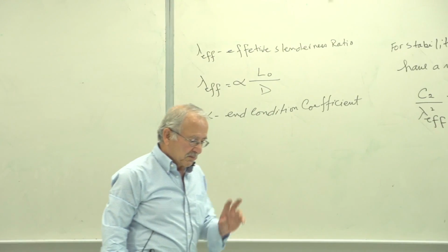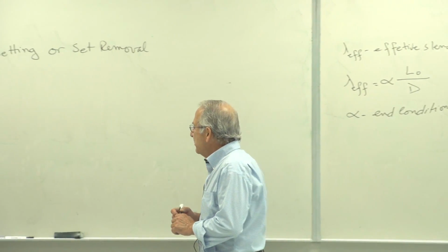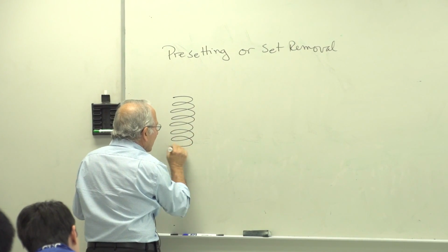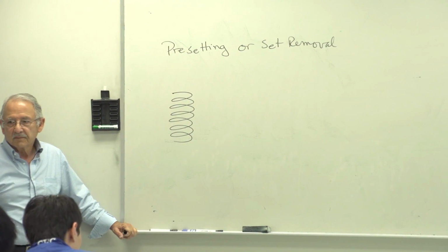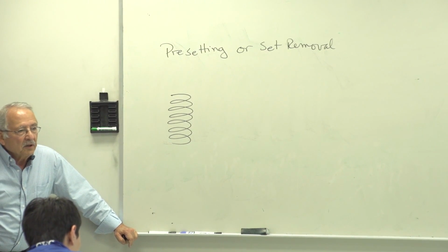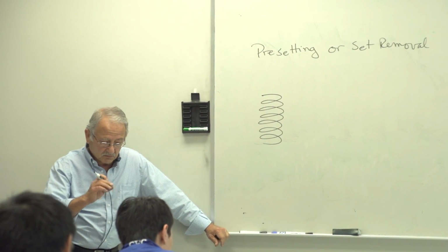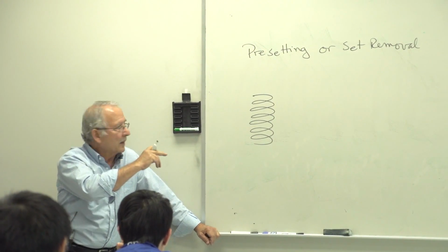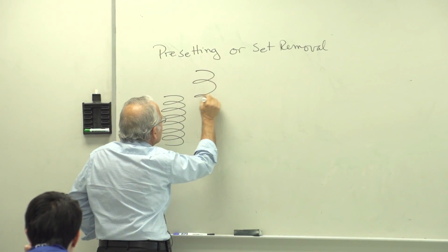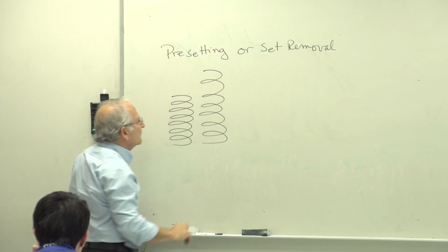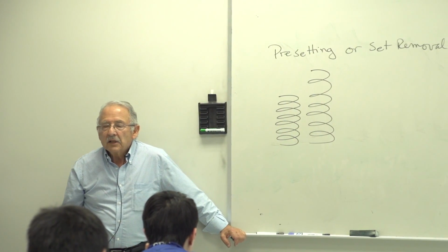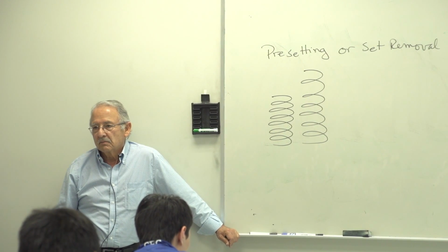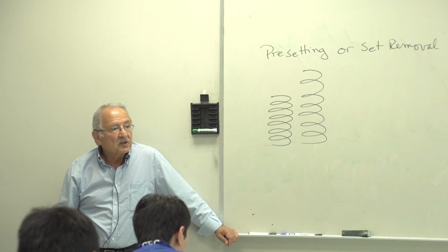And what this means is that if you want a spring of a certain height, you design the spring, and of course you have to make calculations and see what the design length should be. You design the spring somewhat larger than that. And then you put a force on the spring, you bring it to solid height, in which process the spring must yield.